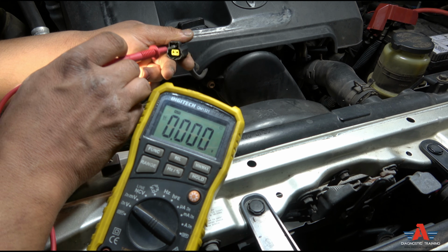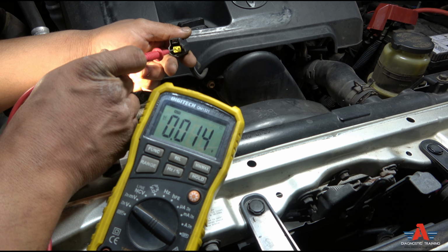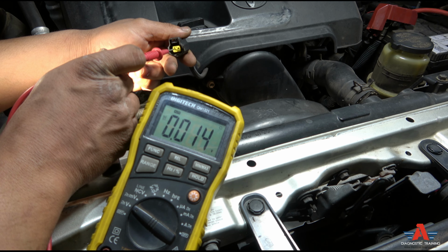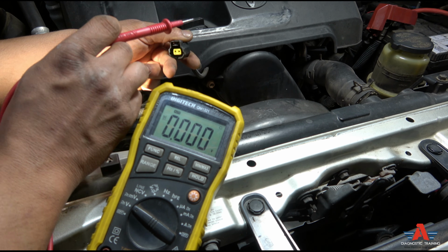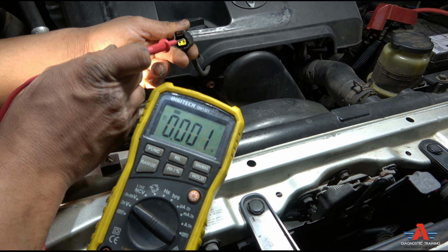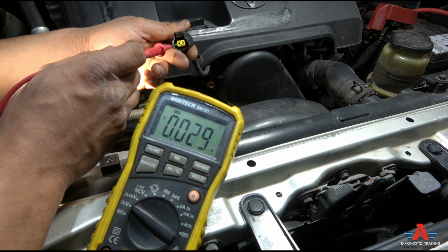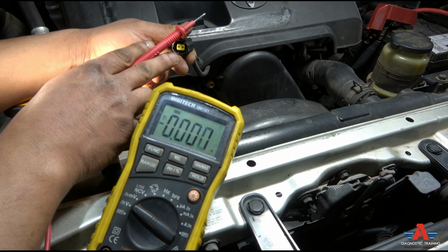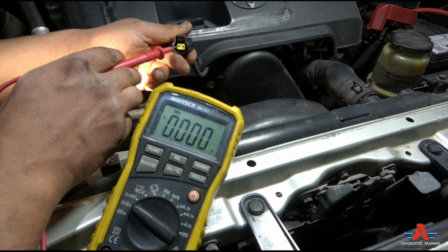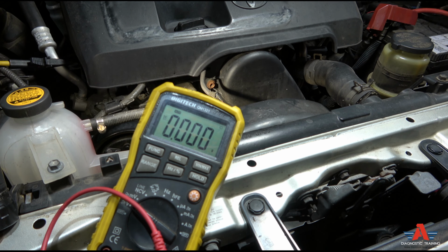But most of the time you don't know. If I put my lead there, is it a 0 volt, or is it an earth, or is it nothing? We don't know. That's why it's best to practice a test light in that sense. Or you can always put 2 multimeter leads on these 2 wires, and if you see 5 volt on the multimeter, like 2 pins in there, you know there's earth and the 5 volt present. But for this test, I'm just going to use a test light.